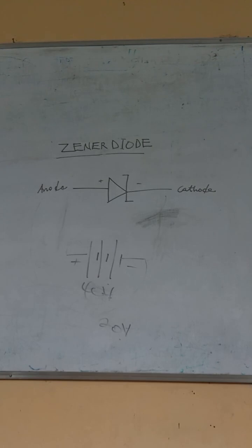Once there is a change in voltage, there will be distortion. So for us to have constant output from the speaker, we need a constant voltage, and that circuit will require this type of diode, the Zener diode, to maintain constant voltage.